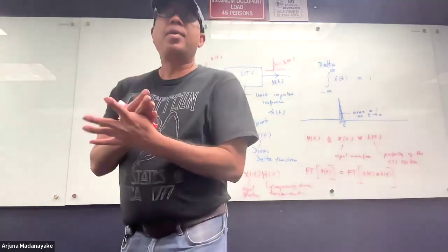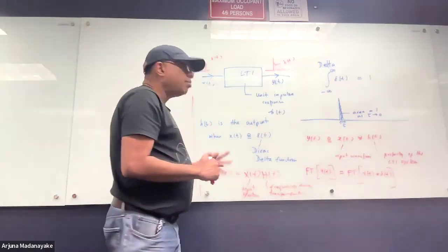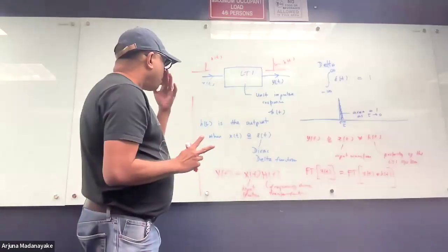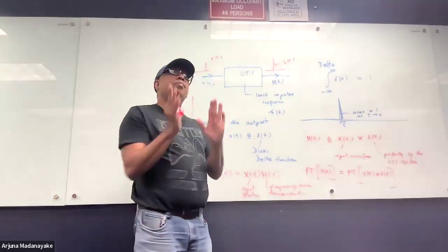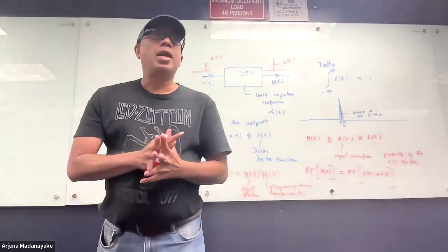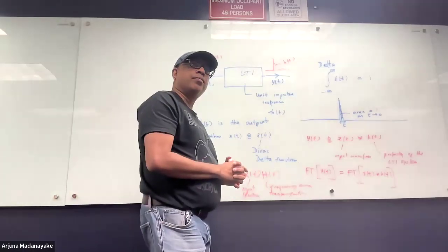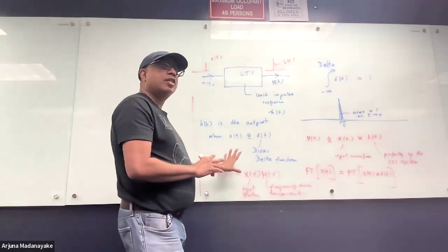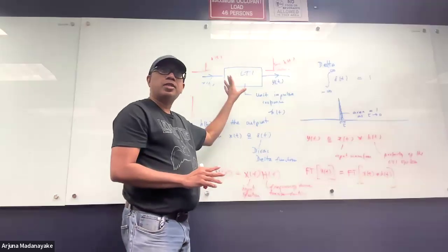It can be Laplace, it could be Z transform, which we haven't covered yet, it could be time, it could be frequency, or many other things. But regardless, in whatever domain, the relationship between the input and output can be expressed in a multiplicative form, in this case h of f. It's not always multiplicative, but it's multiplicative in linear time invariant systems for frequency.